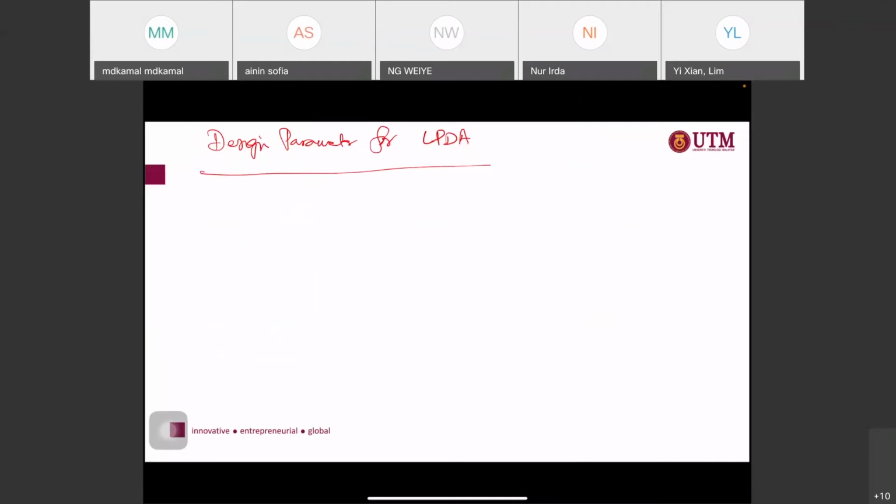So the most important thing here is, as we can see, that Ln plus 1 over Ln is equal to, so that means that this is the length of the dipole. Rn plus 1 over Rn, the distance from the dipole towards the apex angle, Sn plus 1 the spacing between them, Dn the diameter of your wire, and An plus 1 over An.